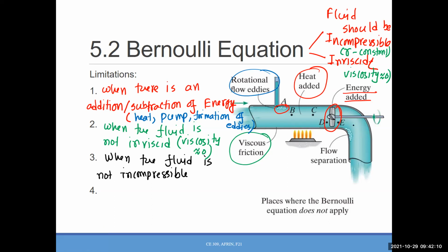when you have a sudden change of the direction of the flow. Usually there is flow separation or something. Flow separation means the flow will not be continuous. Here there will again be a large number of eddies. So that can be the last one, when there are sudden changes in the flow direction.